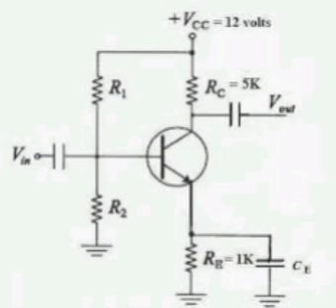With the primary supply voltage held constant at 2500 volts, calculate the secondary terminal voltage when the low voltage winding is connected to a load impedance of 5 plus j3.5 ohms and the transformer delivers its rated current at 0.8 power factor lagging on the low voltage side.